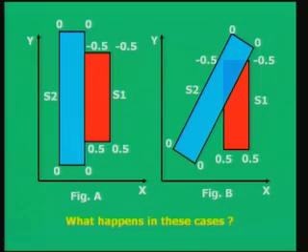And so, what do you do? What do you do for figure B? For figure B, there is no other option. As we did in the previous cases, you have to split one of the polygons in 2 parts: use S1 to split S2 into 2 parts, or you can use S2 to even split S1 into 2 parts. I did say when there are 2 polygons, the reordering can go into an infinite loop. We set a flag and say we reorder only once, but not 2 times, to avoid that.